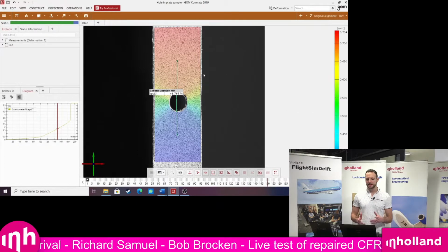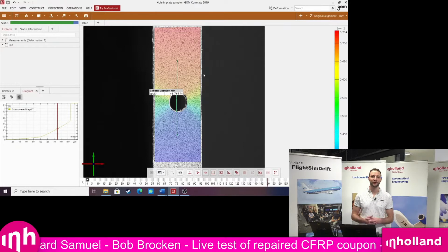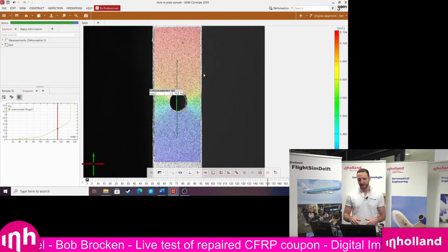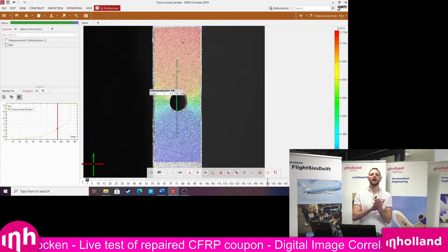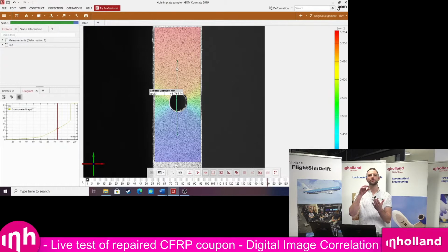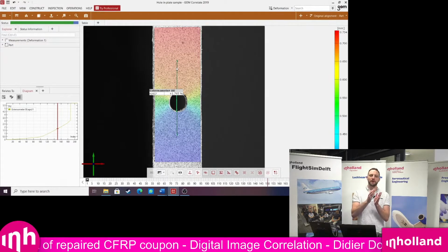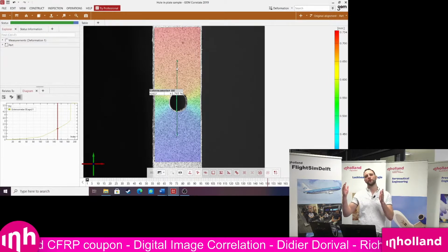So how a DIC system does this, digital image correlation, you're going to hear DIC a lot throughout this whole test, which is just digital image correlation, is that if you can imagine a black speckle on a white background, if you were to zoom in with a camera on the edge of that speckle, pixels are going to go from completely black to gray to white.